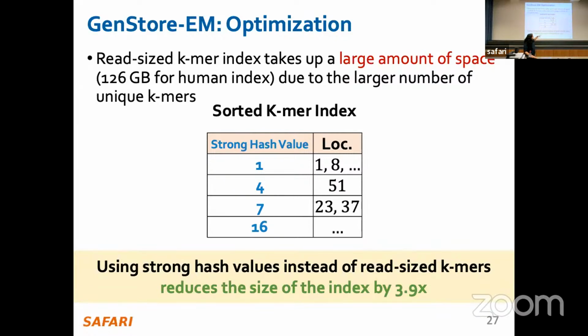But this index is still larger than the baseline index that we saw in the background slide, but that is fine because we have large capacity inside the SSD, and also we can stream through it with high bandwidth because we can distribute it across the channels and read through them concurrently. So that shows an example of hardware-software co-design performed here, specific to the underlying hardware, because the solution is tailored towards the in-storage processing paradigm.